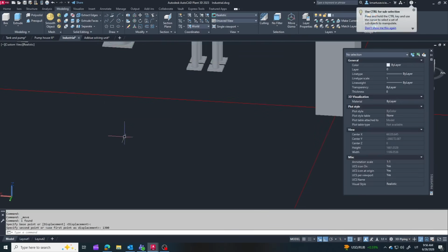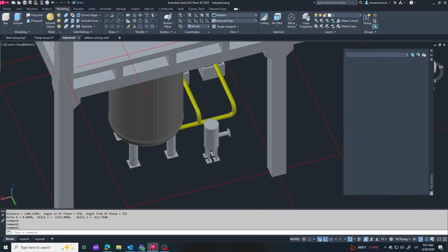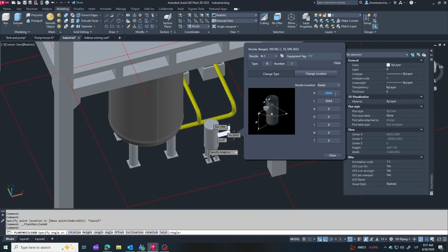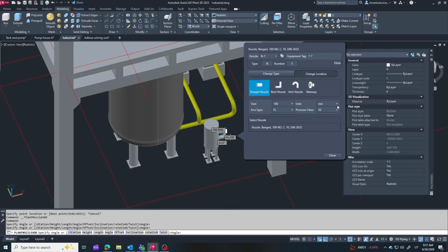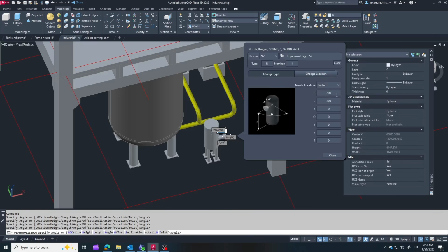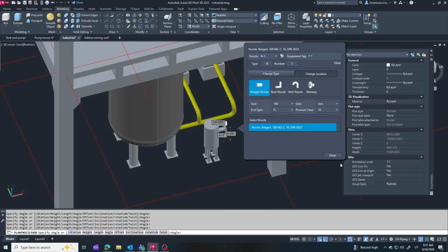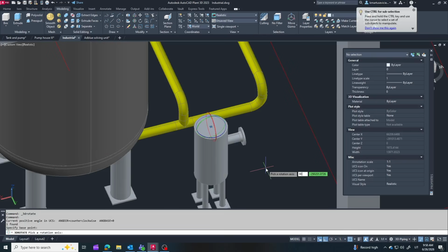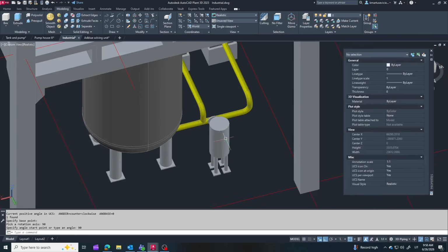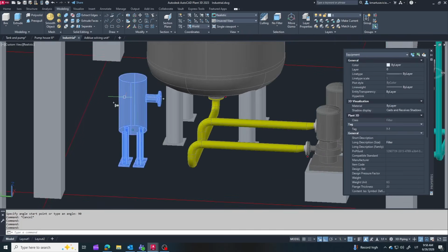From the outside, a basket strainer looks like a simple piece of equipment with two pipe connections. However, its installation requires some planning. Don't mount it too high. During maintenance, the basket has to be removed through the top cover, so it should remain within comfortable reach. Also, make sure the top cover isn't blocked by pipes or other equipment. Always leave enough clearance to remove the basket without dismantling the surrounding piping.